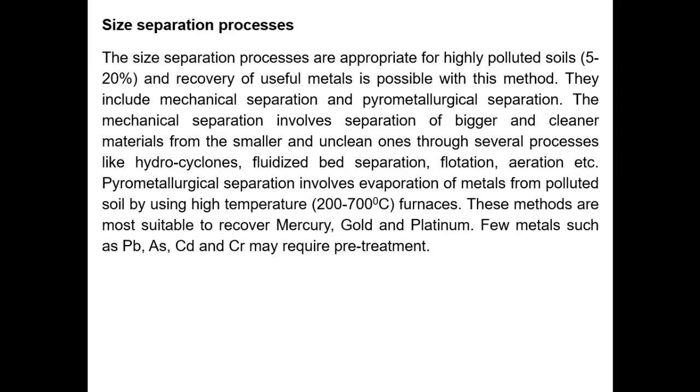Pyrometallurgical separation involves evaporation of metals from polluted soil by using high temperature furnaces. These methods are most suitable to recover mercury, gold, and platinum. Few metals such as lead, arsenic, cadmium, and chromium may require pre-treatment.